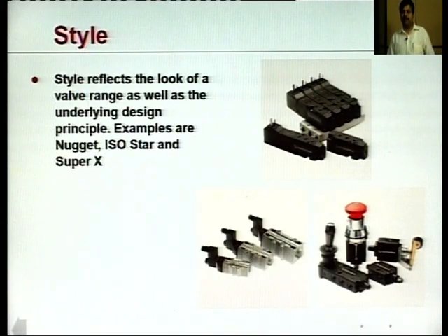Now, let us have a glance at the various types of valves that are actually used in the system and see how they work. These are some of the valves. As we can see here, this is a push button type of valve which is being represented over here. This particular type of system is known as a roller operated valve. This in fact is very useful in the pneumatic systems which are used to make an automatic system. So that whenever there is this movement in this direction of another piston type of arrangement, it in turn causes this valve to operate, which in turn causes movement of that particular piston to be reversed and so on, and a complete pneumatic circuit is built up.